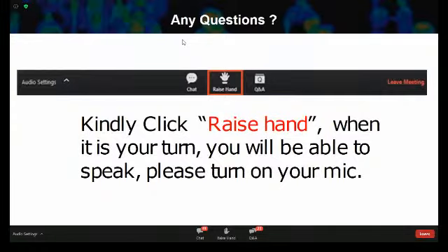Yes, sir, it's normal. The reason is that a thermal camera actually works based on the radiation principle. So if you are facing it directly towards the outdoor, because of the sunlight and all, there is a lot of radiation of heat, so it will detect this heat. Also, whenever a person comes from the sunlight, their temperature will be naturally high. So it will give you a false alarm.